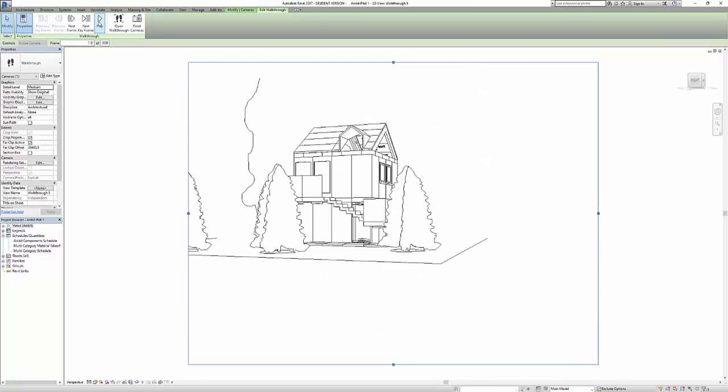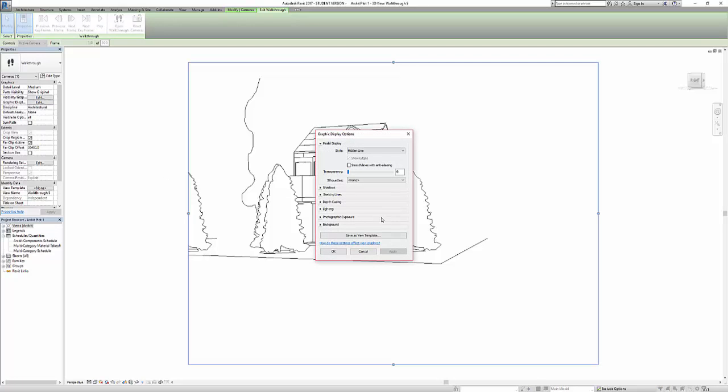You will notice that my walkthrough had a number of times where all you could see was white space because the viewer was walking away from the building. To minimize these, try and establish a camera route which will maximize the time you're spending looking at the Arckit build. With that complete, you can now choose under the Properties, Graphic Display Options, click Edit, and you can now